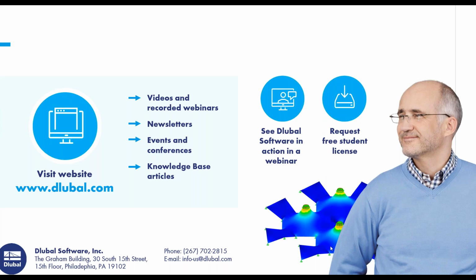I'm pretty sure we don't do... Oh, yeah. The add-on module extension RF-DYNAM Pro Nonlinear Time History will allow for nonlinearities to be considered for time history analysis. This is a module extension, so you have to have the RF-DYNAM Pro Forced Vibrations module. So yes, that's right, it is possible.